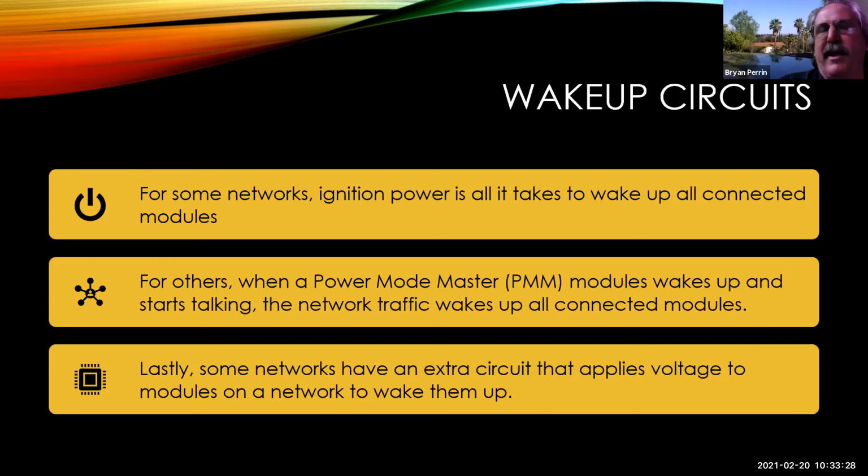Right. And the manufacturers that do this also send some neat codes, because it sends a wake up signal and then it doesn't see the module. So the master module's doing both things, right? It's sending out a wake up signal and saying, hey, I called him and he didn't pick up the phone. And so now the question is, is the wire broken in the network, in the wake up signal?